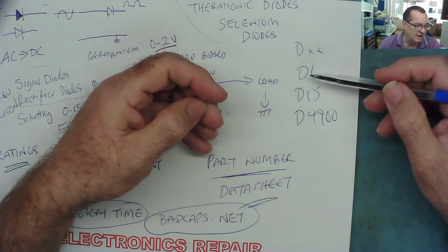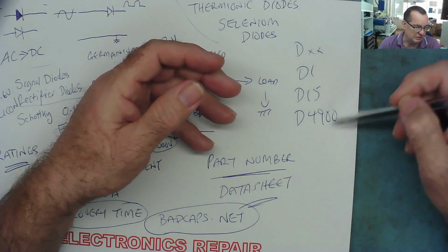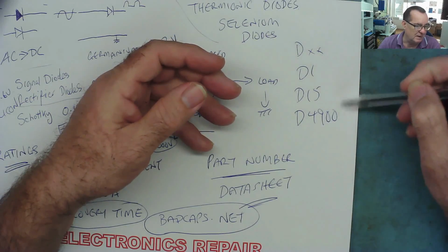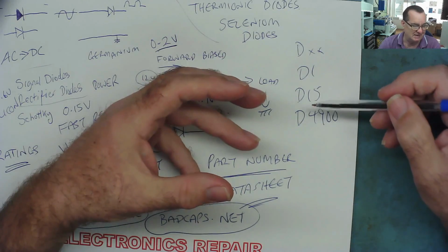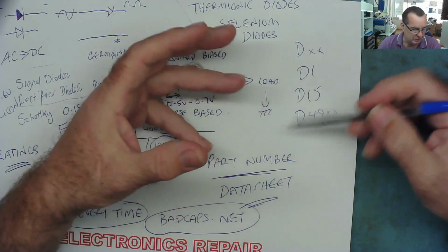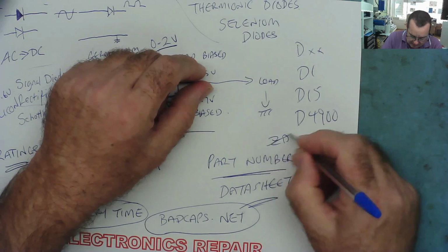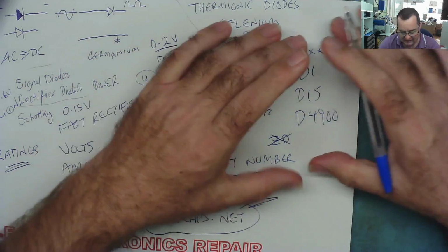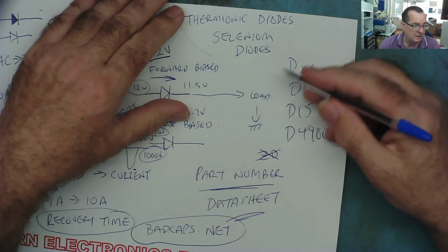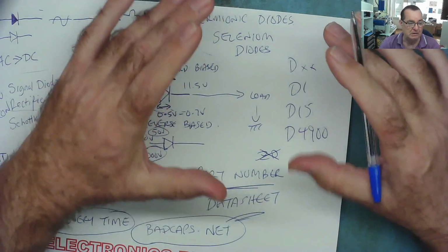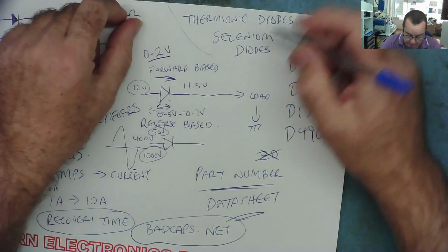So you'll often see D this, D that, D the other. That's quite a good way to tell if a component actually is a diode. You'll see others more specialised like ZD, which is a Zener diode, and others, but at the moment we're just talking about diodes, so that's how you recognise them on the actual silk screen printing, if there is one on your PCB.